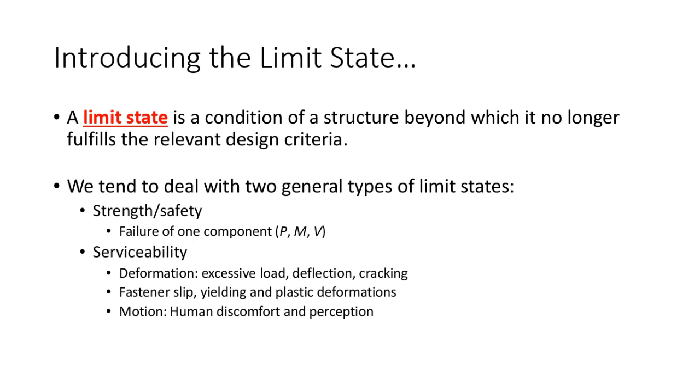Now, when I'm a structural engineer doing this, I have no idea who this Dr. Michelson guy is and what he's going to have in his office. I have much more uncertainty associated with those occupancy loads than I do the dead loads. If I know that concrete weighs X number of pounds per cubic foot, and I know the slab's going to be so many inches thick, I can compute the weight of the slab, and the weight of the beam and the carpet and all of that. I have much more certainty about the dead loads than I do the live loads.